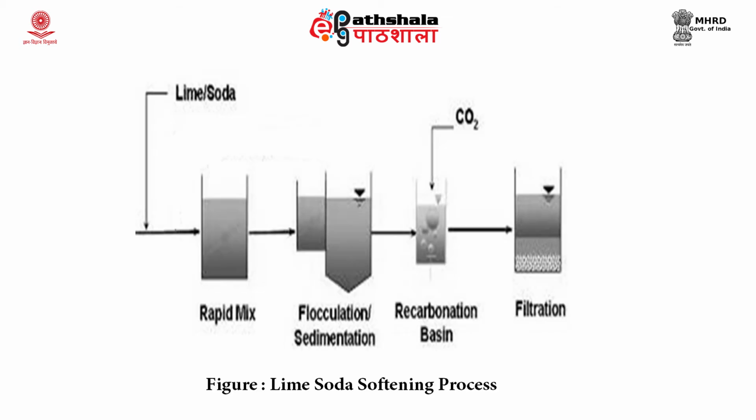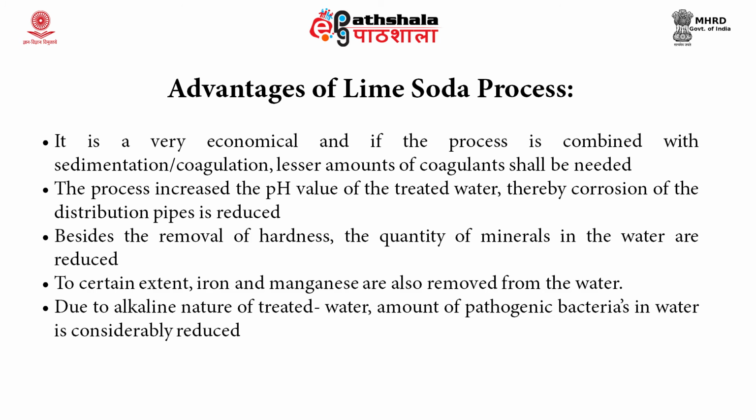It is not possible to remove all the hardness from the water. In actual practice, about 50 to 80 mg per liter of calcium carbonate equivalent hardness will remain as the residual hardness after the treatment of the hard water through this lime soda process. Let us discuss the advantages and disadvantages of the lime soda process.